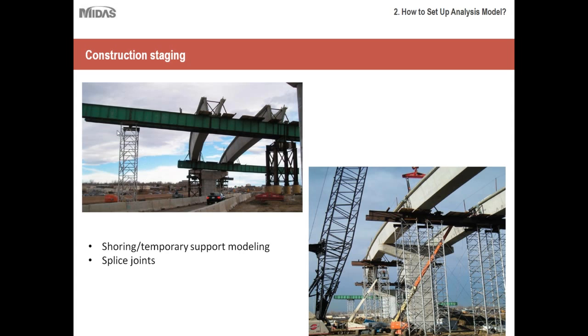So instead of just applying a point support and getting the camber value for the superstructure, you would have to model the entire system underneath it, something like this, and then assess the forces.